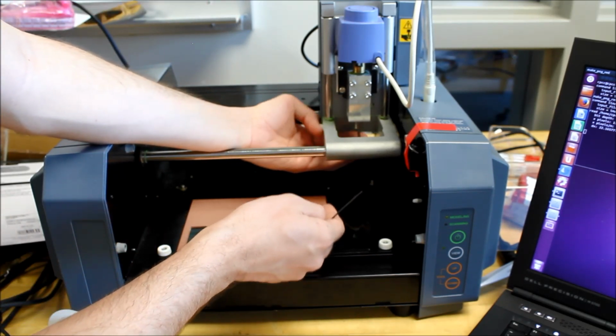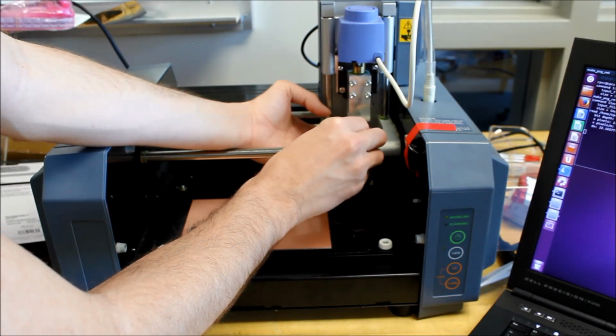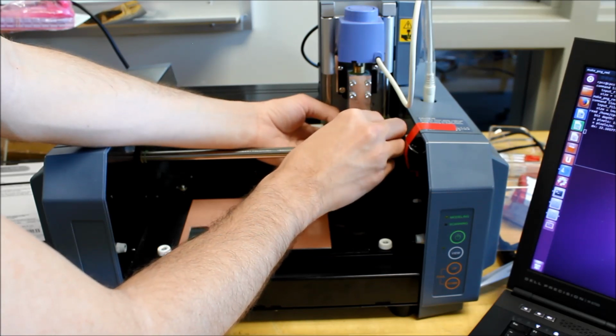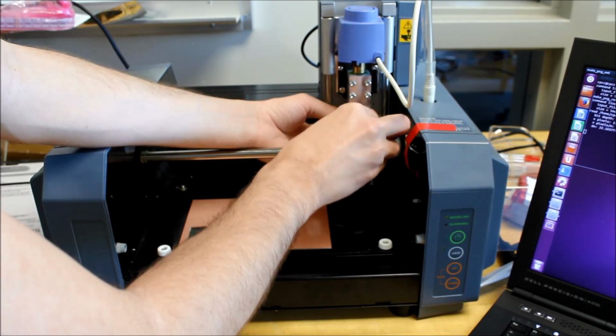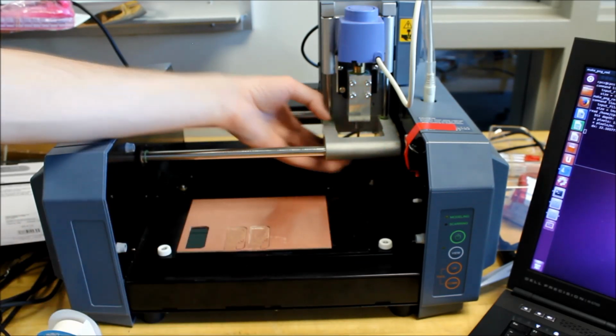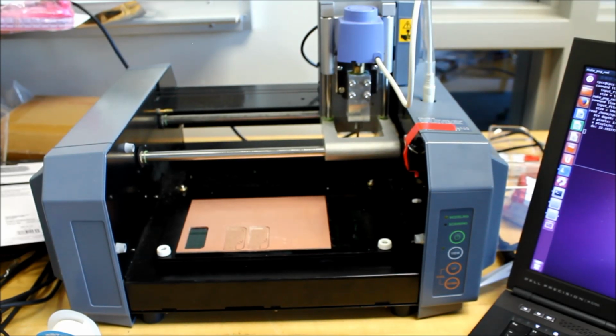But what this is going to do, by having the end mill deeper than I need right now, only by a few millimeters, is give me some slack whenever I go to align it. So now the end mill is in place, and I'm ready to move the drill bit to the offsets for my X and Y before I begin my cuts.